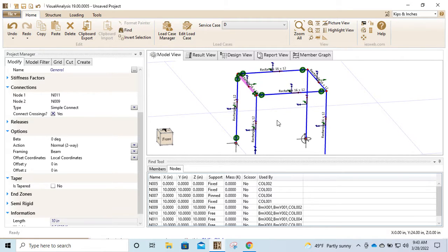It's going to give you results, but as Adam showed on that one, it was a frame that looked just like this, right? And what the person had done was fixed the beam in one direction, so it had moment resistance, but then in the other direction it was all released, right? So this thing would just lay flat. And it did lay flat, right? These nodes traveled 7 light years out in one direction, because the stiffness was so small that the displacements it ended up calculating were massive. So again, going back to validating your models, does that even make sense? That would not make any sense.